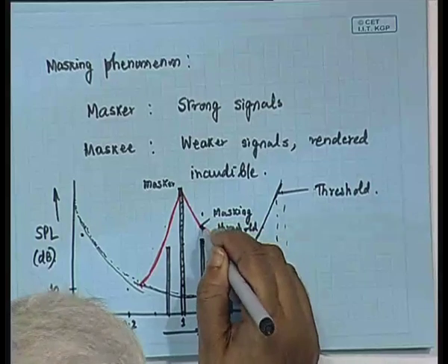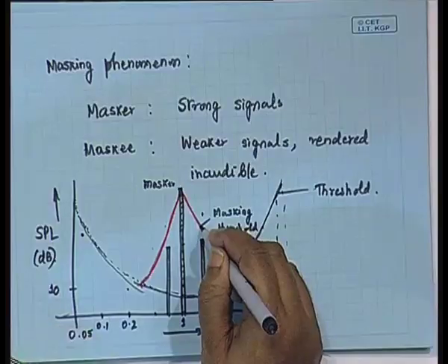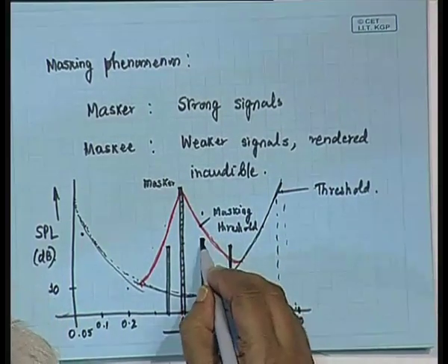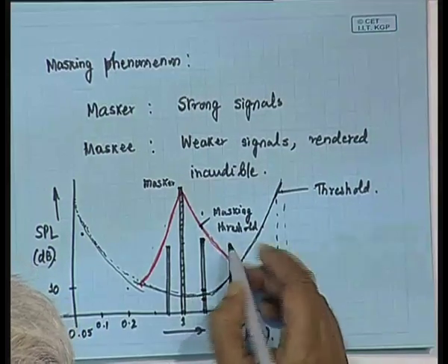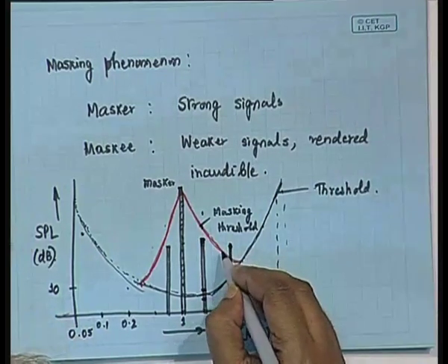So, you can afford to keep a lower number of bits, and can afford to keep your quantization noise sufficiently higher. Whereas, say this much of quantization noise will be inaudible for this frequency, but at this frequency if the quantization noise is this much, then it gets audible.